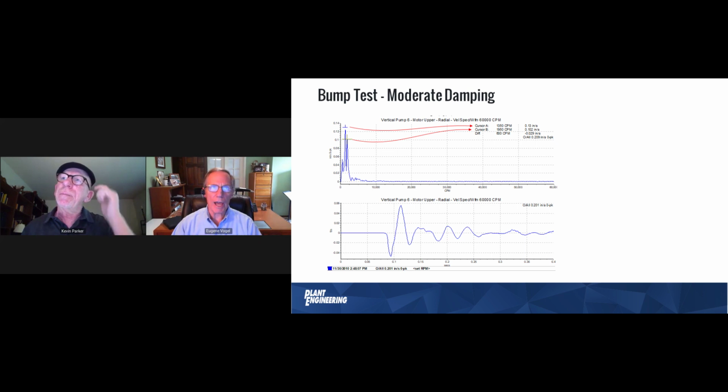I think what you said is accurate. If you wanted to know more about that, I would explore something called Bode plots, capital B-O-D-E. A Bode plot is generated as you change the speed of the machine and you record the amplitude and phase at each different spot.